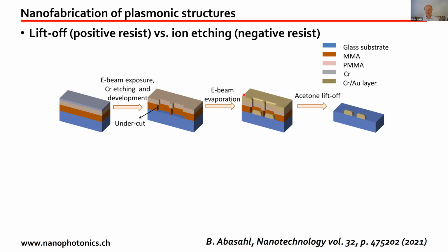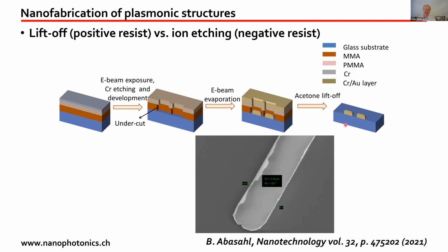As a consequence, when you evaporate the metal, there will be a discontinuous film between what is deposited on the substrate and the remaining, such that the liftoff occurs very well. If you put only 1 layer of photoresist, when you do the liftoff, this continuous film will usually tear apart, and you have structures that are not very well defined.